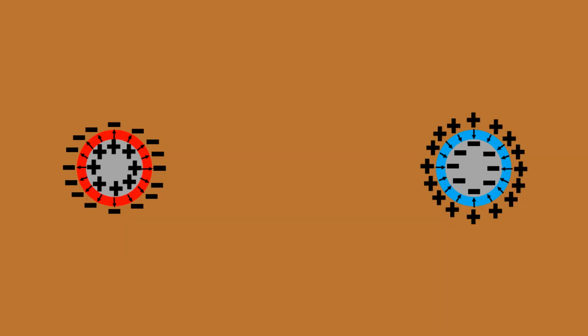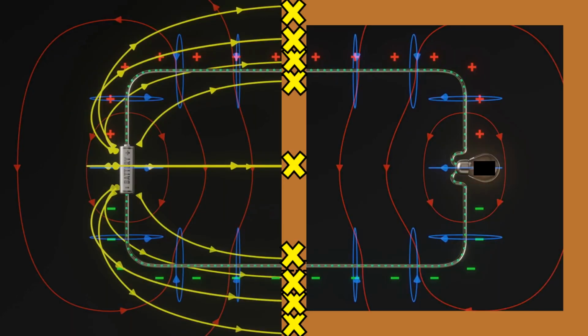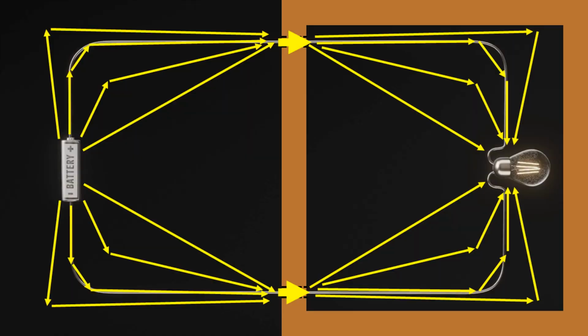You could completely eliminate the gap between the edge of the hole and the insulation on the wires, but the electric field would only become all that much stronger, leading to the same amount of energy transfer. So instead of blocking the Poynting vector, the copper box actually redirects it, with the same amount of energy being delivered in both cases. This may lead you to ask, what if we made the holes even smaller by removing the insulation from the wires?